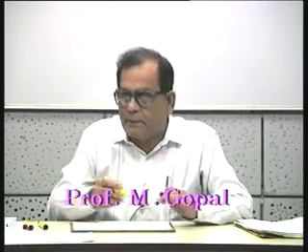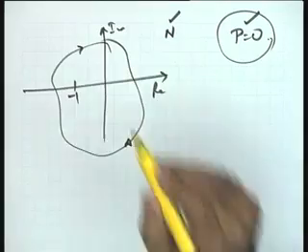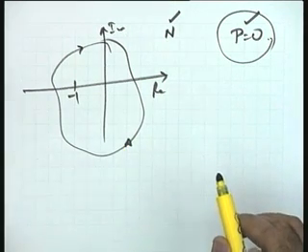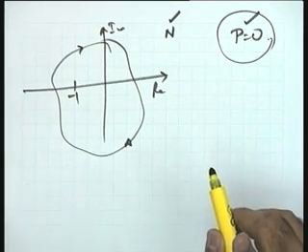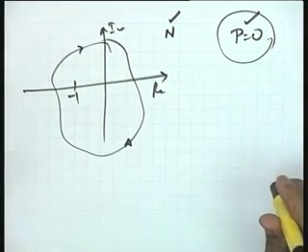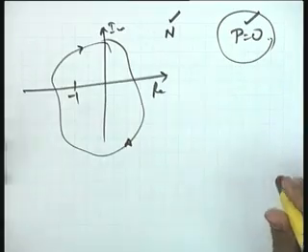P is equal to the number of poles of the open loop transfer function which are there in the right half plane. Normally, you will come across situations with p equal to 0, but in general, once you know n, you require the information on p to get the conclusion on the Nyquist stability criterion. So, in this particular case, you find that n is equal to 1. Is it n equal to 1, please? n is equal to minus 1, because n has been defined as the number of encirclements in the counterclockwise direction. So, n is an algebraic quantity. That point may please be noted.